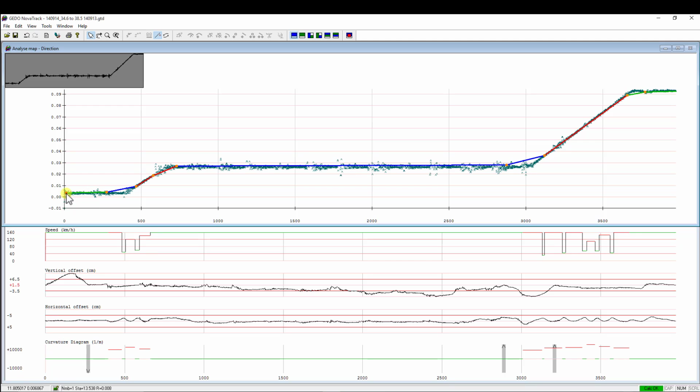If you go to the beginning of each straight element, move the mouse over the split point and press the A key, the element will be automatically adjusted through all measured points. The same we do for the next straight element, and the same for the next.